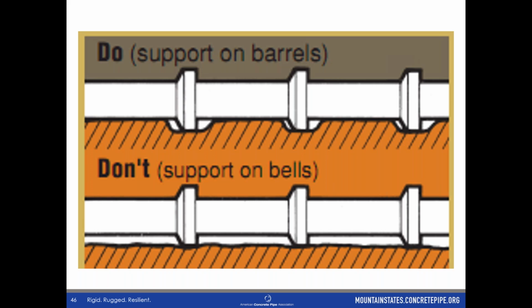Also, you want to sometimes make sure you're digging them depending on the size of the pipe and how you're putting them in. If you're lifting that pipe into place in the middle of it, you want to dig a little hole underneath so you can get the choker out. So that's always important. But what happens is if we don't dig bell holes and we put loads on it, we know that these pipes are going to act basically as beams, right? They're just going to be little beams, and we know that beams, when a load is placed on the middle of that, they want to deflect. We also know that concrete pipe does not want to deflect. So what does it do? We start seeing cracks in the middle of the pipe, just like this.